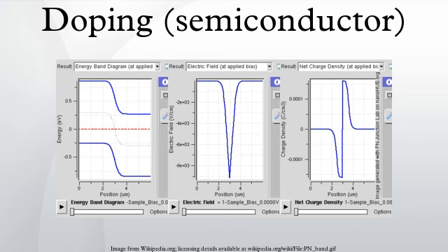Effect on band structure. Doping a semiconductor crystal introduces allowed energy states within the band gap but very close to the energy band that corresponds to the dopant type. In other words, donor impurities create states near the conduction band while acceptors create states near the valence band. The gap between these energy states and the nearest energy band is usually referred to as dopant site bonding energy or EB and is relatively small. For example, the EB for boron in silicon bulk is 0.045 eV, compared with silicon's band gap of about 1.12 eV. Because EB is so small, room temperature is hot enough to thermally ionize practically all of the dopant atoms and create free carriers in the conduction or valence bands.